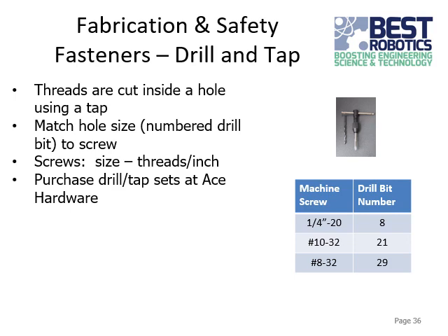What tapping a hole means is basically you're taking a hole and using this tap that will actually cut threads into the hole, so that when you're done, you can screw a screw into it. You don't necessarily need a nut on the other side or anything like that, because the screw will fit perfectly where it has to screw in. A lot of times these will come in sets with taps and the corresponding drills that go with them, so that the drills are the right size for the tap. You can get those at a hardware store.